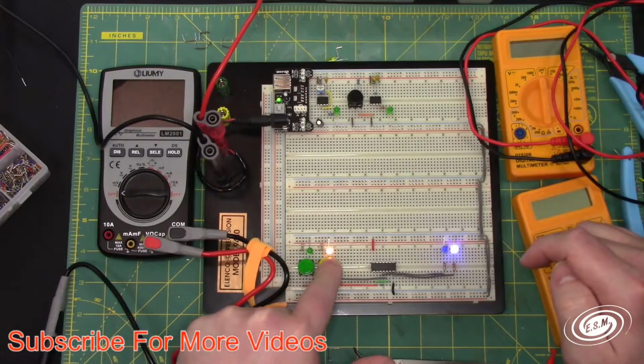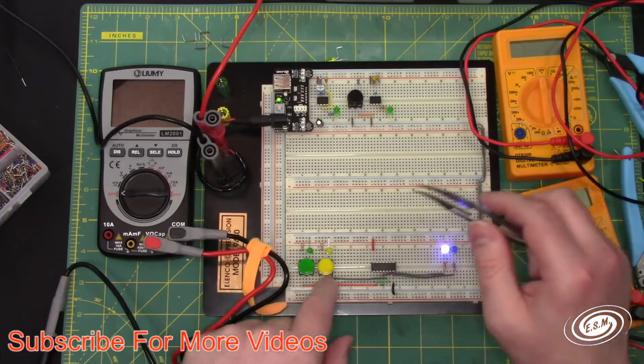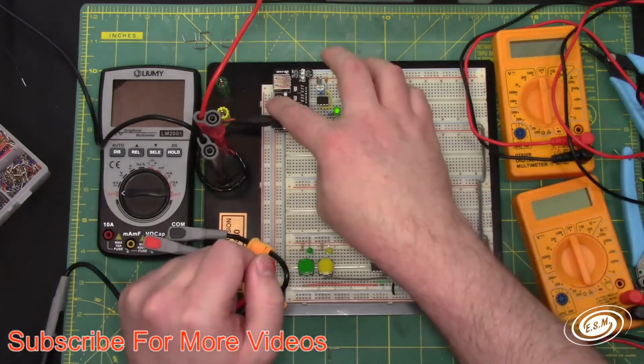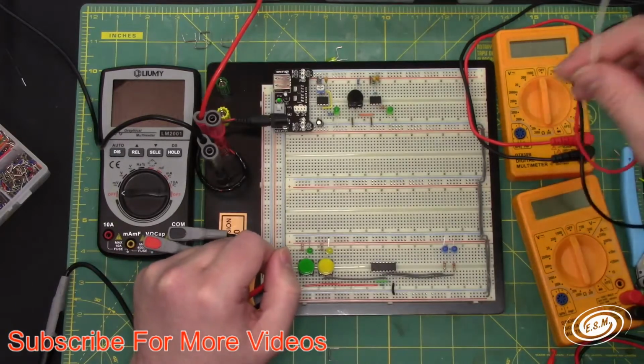So it is almost similar, but I had to use a pull-up resistor and connect the LED to ground, so I had to reverse the switch order. But that is that.